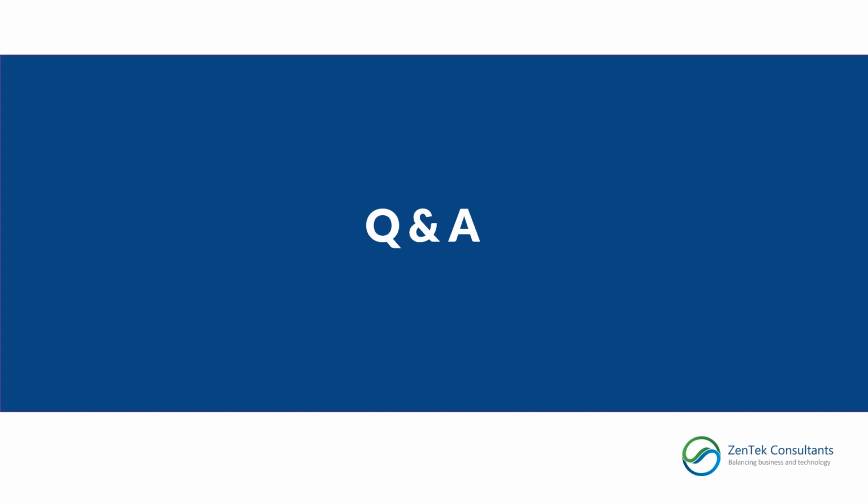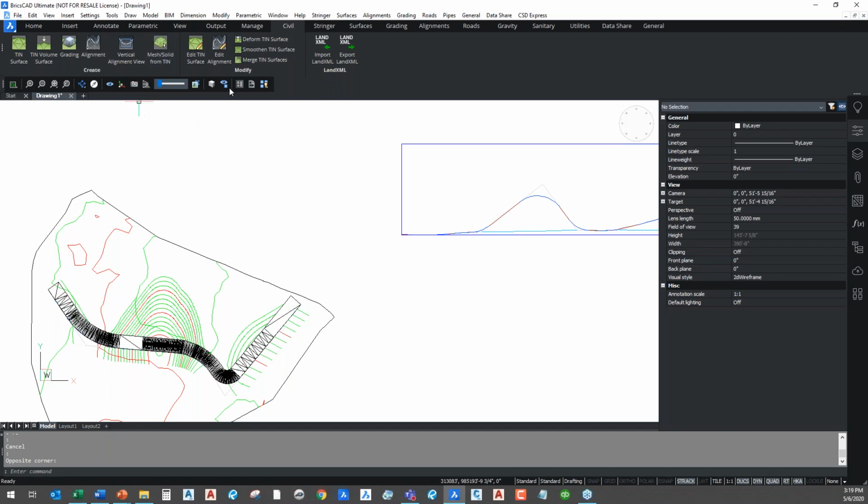Okay, and the last question that I see is from Farid, and I hope I pronounced your name correctly. Can I add high and low points for drainage? Yes, absolutely. Like I said, you're working in there. You can easily add points at any elevation manually to your surface, right? Just to jump back real quick, you can see up here, I have the ability to go in and add points wherever I need them, right? So I can just go in and add and modify individual points, right?